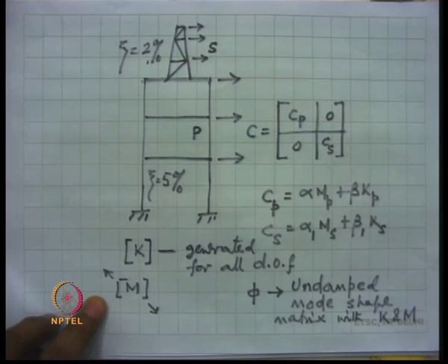Once we get that, then one can use the usual response spectrum method of analysis, because we know the modal damping for each mode of vibration.